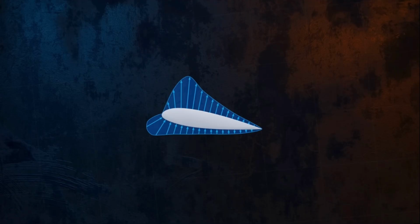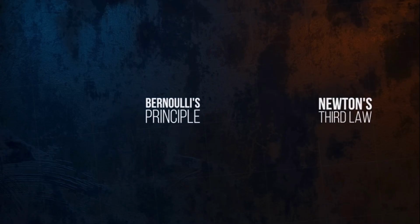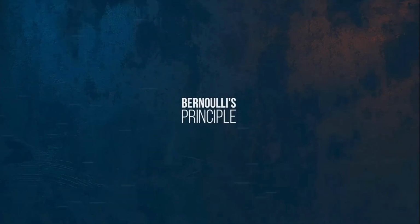So we know that lift is caused by the pressure distribution around the airfoil. But where does the pressure distribution come from? The answer to this question is complex, and there's much debate about the best way to explain it in a concise way. We can broadly split the different explanations into two groups, those based on Bernoulli's principle, and those based on Newton's third law. Bernoulli's principle explanations focus on the velocity of the fluid.